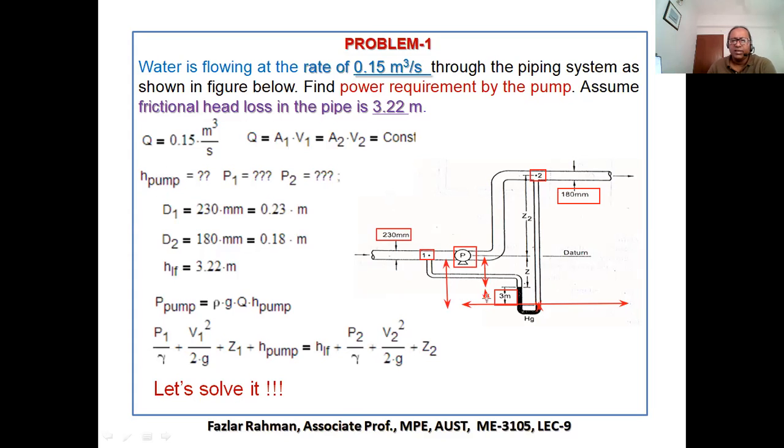And you see, Q is given, and the diameter of the pipe on both sides is given. So you can figure out the velocity at point 2. How? Q equals A V. You can figure out the velocity right over here. So if we apply Bernoulli's equation between these 2 points, then what do we get right over here? At point 1, the fluid has this much energy.